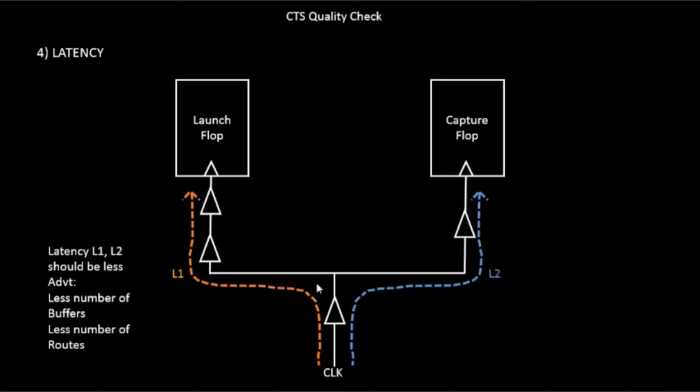First of all, it will reduce the number of routes, and the second advantage is the runtime reduction, because building this tree will itself take an amount of time. If you plan your clock tree beforehand, you save an amount of runtime over here. It's a clear 10x reduction. And that too, we have thousands of flops sitting in a small area. So if you multiply the runtime by 1000, you see the amount of time you save by building a clock tree.